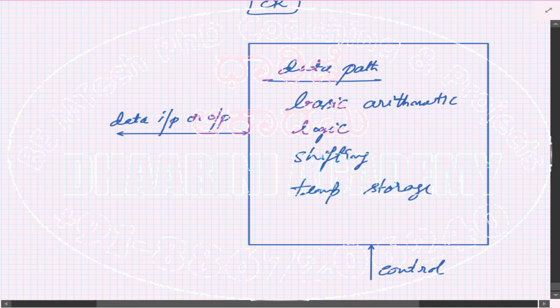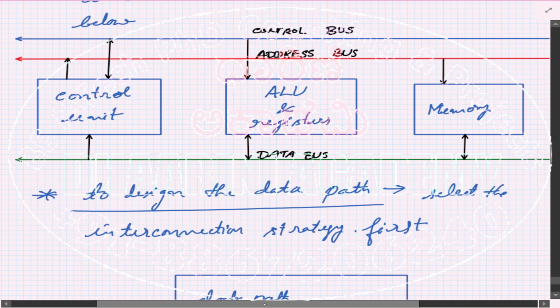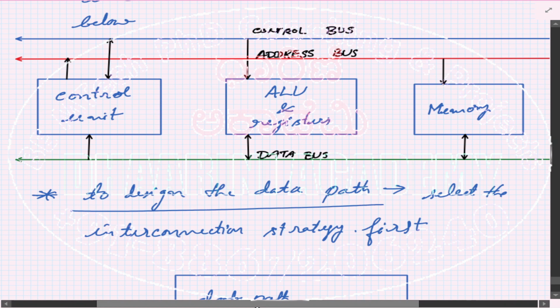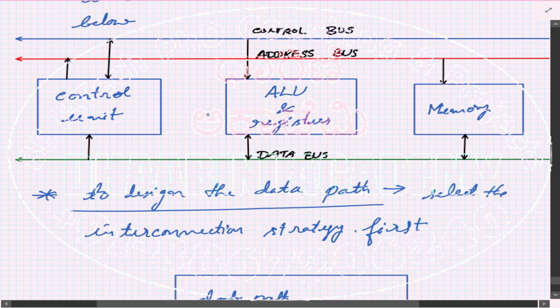Once you choose all of them according to your requirement, I come back and check. I have shown here that these are my 4 units and I need to make the connections accordingly. So first, for each of the blocks, connect only the data bus, in the sense only this line I connect for every block. And also I will connect the control signal.